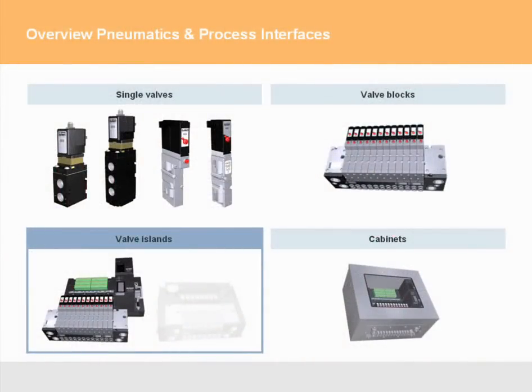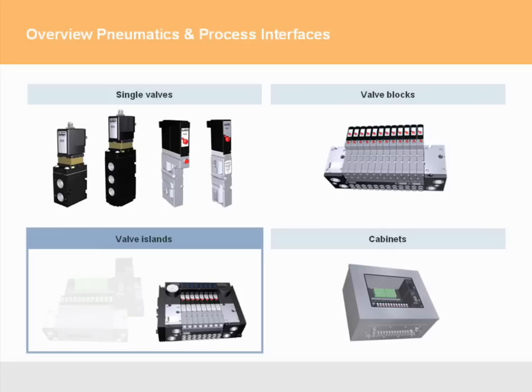Different to the Type 8640, the airline system Type 8644 can not only process digital but also analog signals. Overall, Type 8644 offers more functionality concerning modularity, data processing, and Fieldbus techniques. Altogether, up to 64 valve functions may be combined together on one airline system.